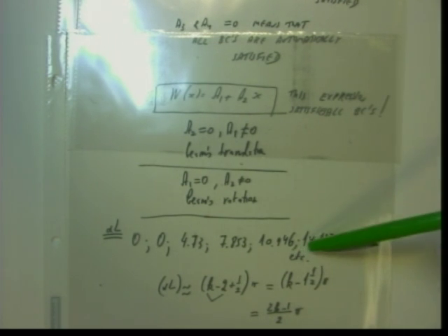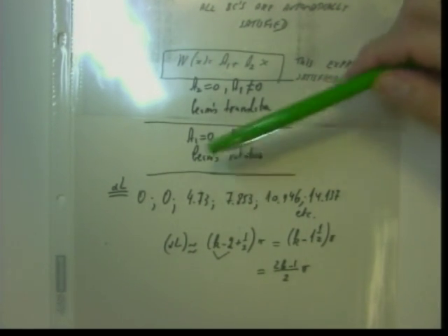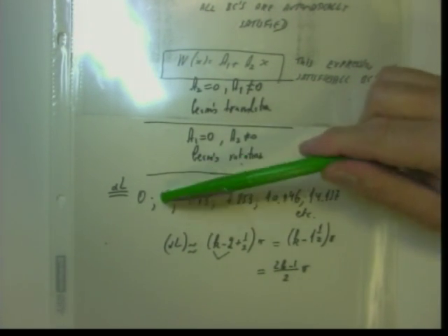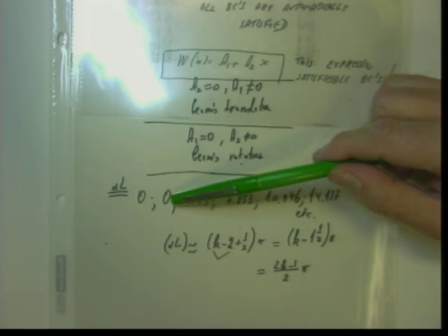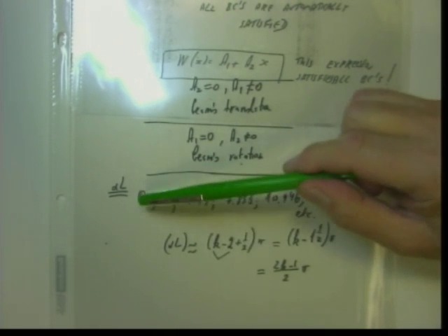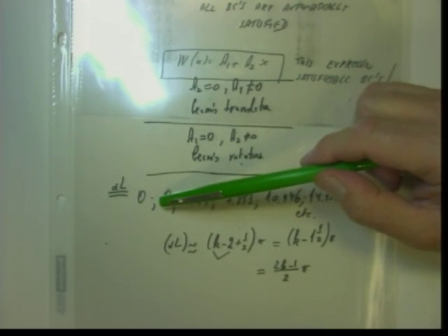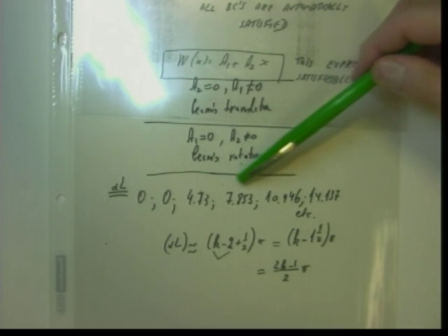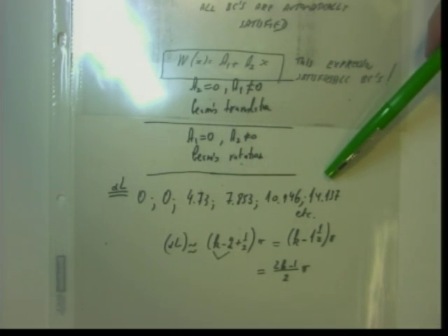So actually what happens is as follows. The natural frequencies of this beam are 0, 0. So this beam has 2 zero natural frequencies. That is translation, this is rotation. And then come natural frequencies that are associated with the clamped beam. One can show that the same characteristic equation is obtained.